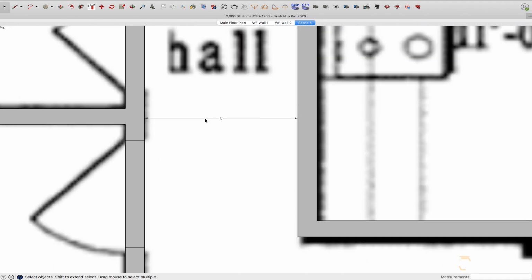One thing to keep in mind is that many municipalities require hallways and doorways to be a particular width to ensure buildings are accessible and easy to evacuate in the event of a fire. This is why it's typically best to leave the dimensions of the hallways unchanged to maintain a wide enough corridor for ingress and egress, especially if the plans you're starting with are already code compliant.